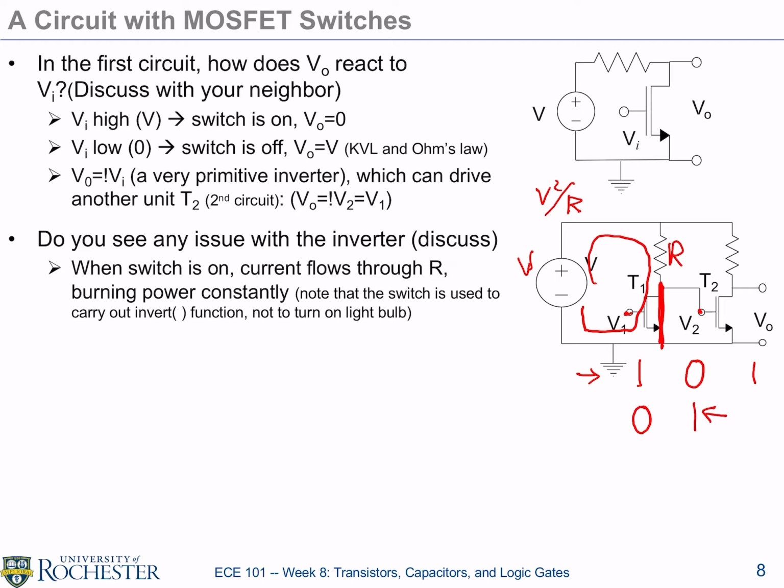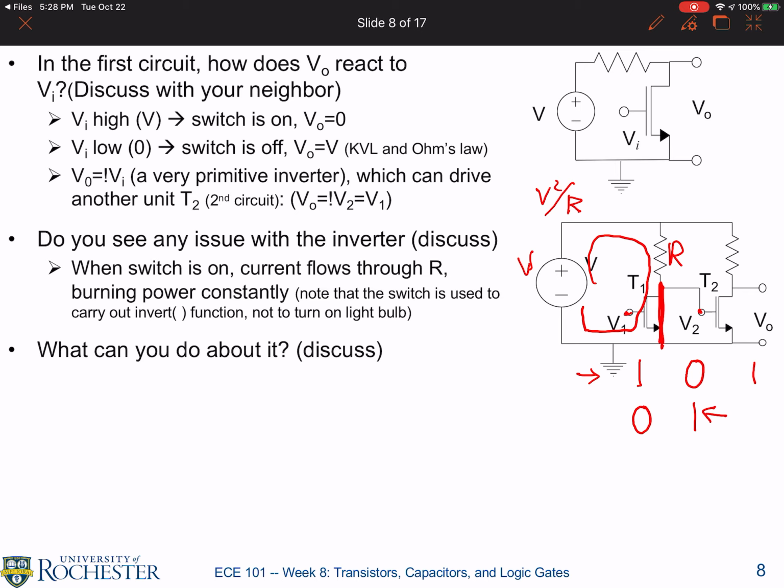So if you think about a possible solution, what we wanted is really this. Why do we have the resistor over here? Well, that's a load, if you wish. What if I turn that to 0? It's a problem. If this is just a piece of wire and V1 happens to be high, then I burn my power supply. The current would be too high. So we don't want that. We don't want this current to be high. That's why we have this load.